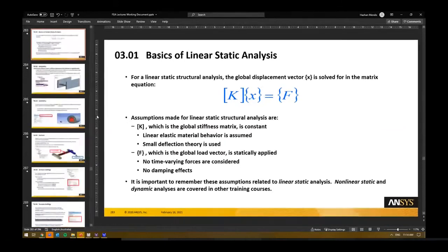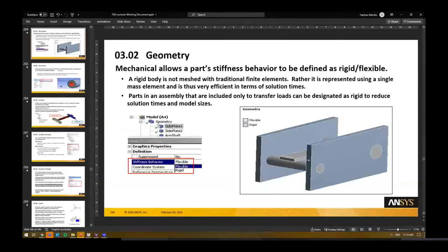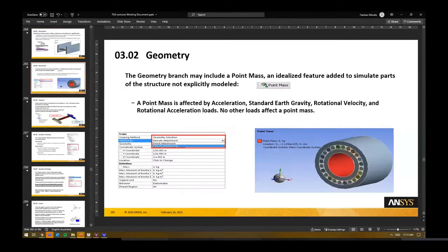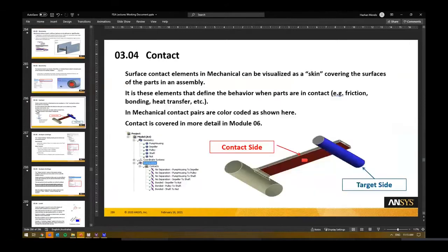All right. So I've actually talked about this. Most of the geometries that we've been playing around with are all flexible geometries, so we can look at stress and strain on them. We can specify things as rigid as well. So it'll generate surface elements where we've got things like contact, and then everywhere else it won't actually determine things like stresses internally on our actual object, right?